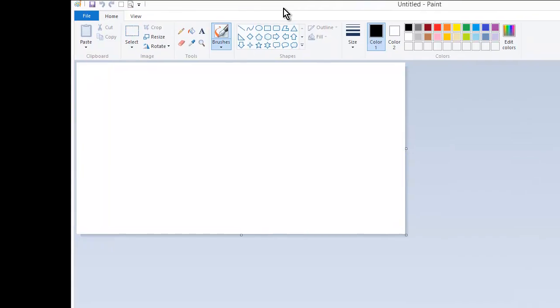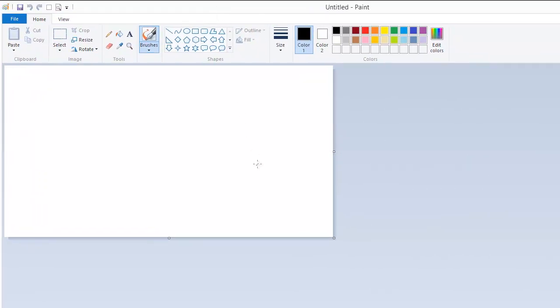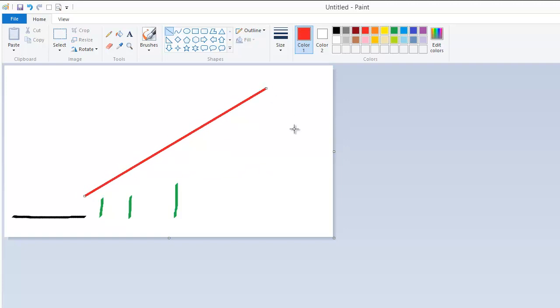Let me move in a whiteboard here where I can draw. Let's say we have a runway represented by this black line, and we have some obstacles here at the departure end of the runway. Now, about 10 years ago, TERPS and PANS-OPS had essentially the same criteria for departure procedures. And departure procedures at that point in time all began at 35 feet above the end of the runway. So you would have a departure procedure that looked something like that.